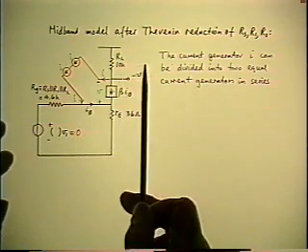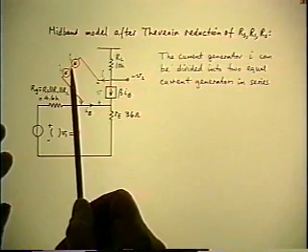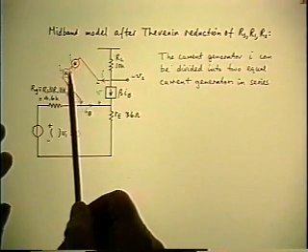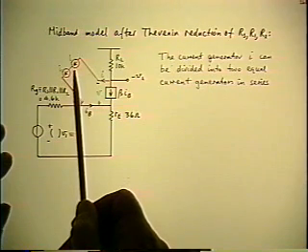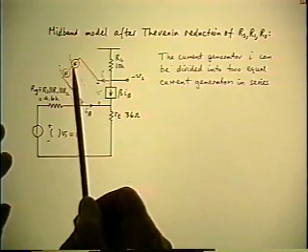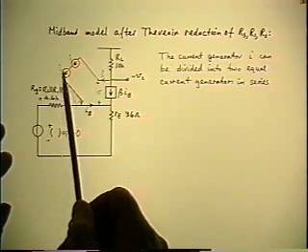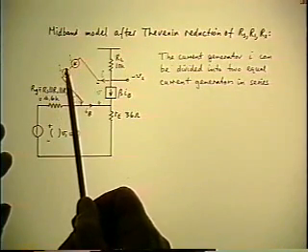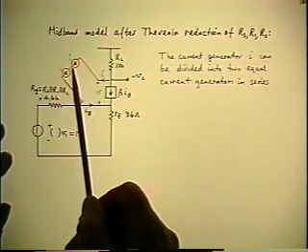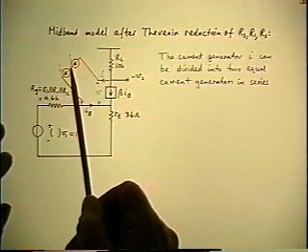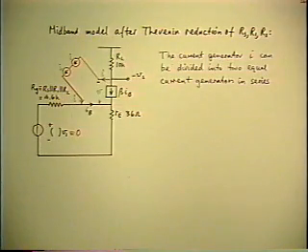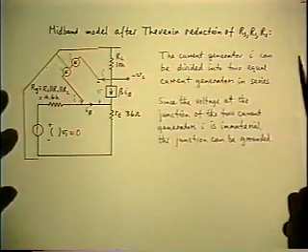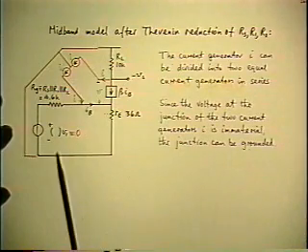But we have now developed, at the connection between the two current generators, a new node whose voltage is arbitrary, because by definition the current generators are going to pump the same current regardless of the voltage across them. So I can give the voltage at this node any value I like. As usual, the simplest value to choose is 0, ground in this case.